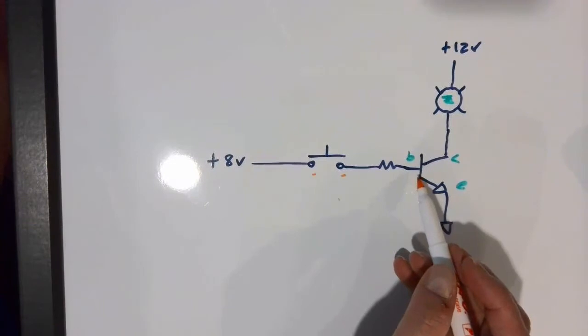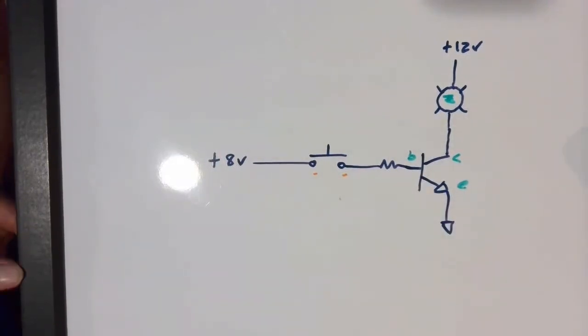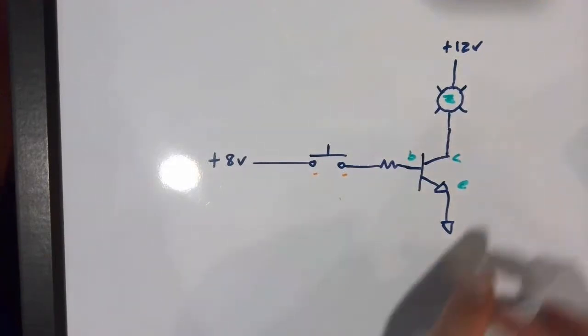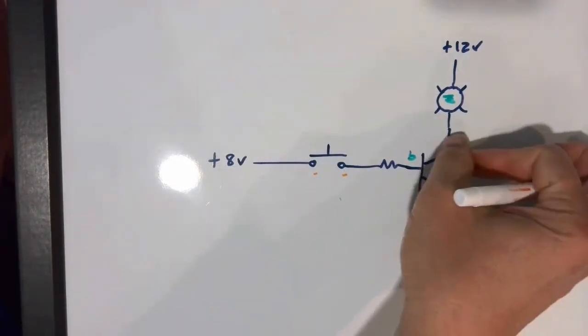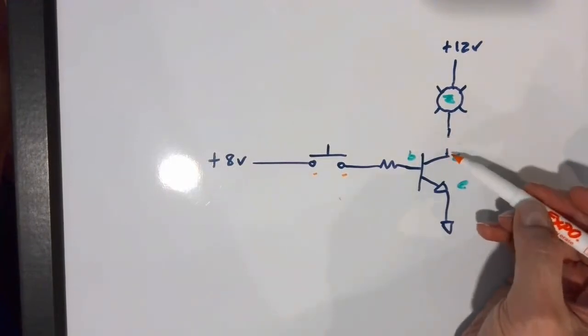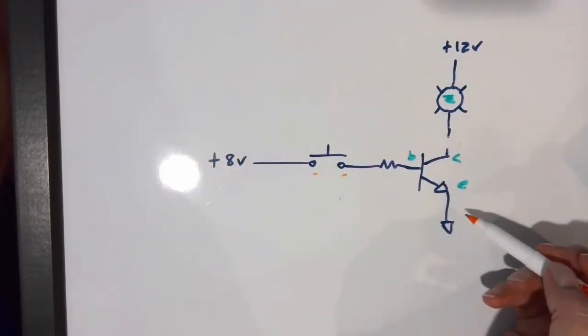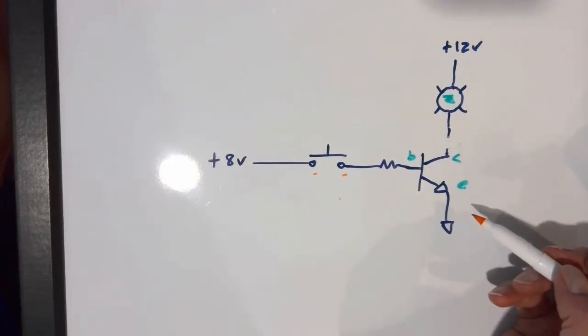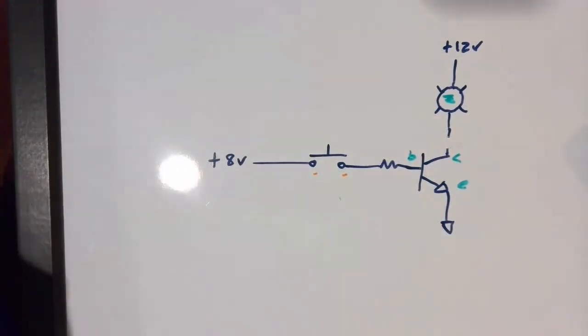and no current flowing into the transistor itself. In that case, in this circuit, this transistor is turned off, which essentially means that it is completely disconnecting or opening up the output here from the collector and allowing no current to flow through the whole device. So that is in the off state, and we can use that to turn the output off.